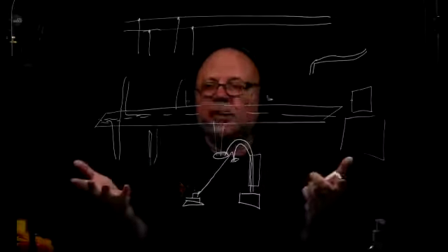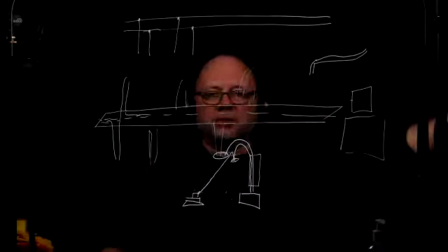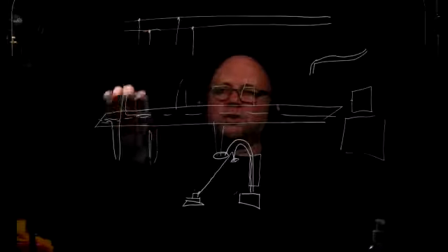So there will be a service loop. So the way you do it, if it's in the hallway, if it's a long hallway, you're just going to put the box on one side of the hallway. You're going to run in the ceiling all the way to the back. And then you're going to fasten the end of that somewhere so it doesn't run back when you pull it. And then you're going to pull the slack wherever the speakers are going to be in the ceiling.